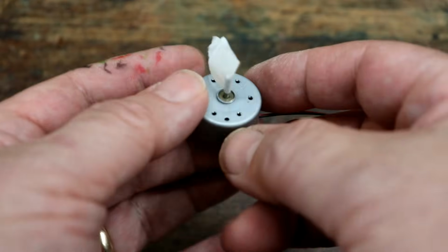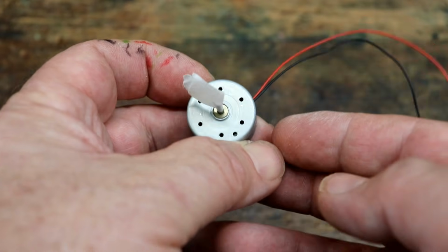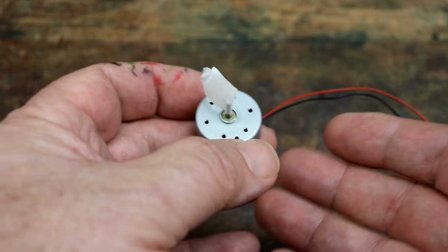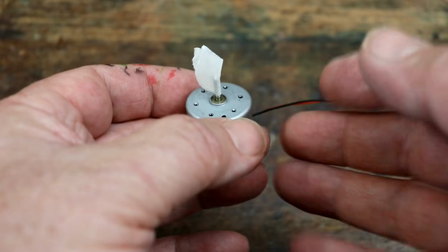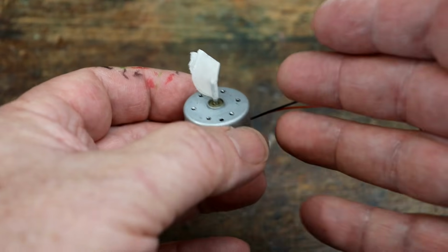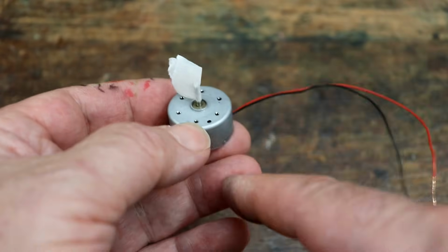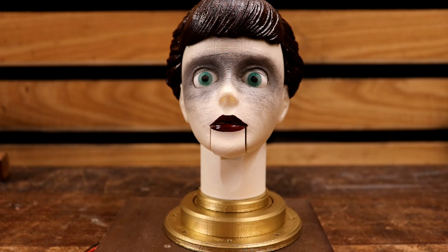What a mess. The second type of motor is a little DC motor, and this is used to open and close the eyes. I could have used a solenoid for that, but it would mean that it always needs to be supplied with electricity to keep the eyes open or closed, whichever way it was mechanically connected up. This is great because it just needs a really short pulse to get it to open the eyes one way, and a really short pulse in the other direction to close the eyes, and then they'll stay open or closed.